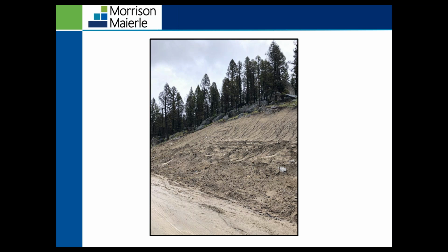So the contractor here was only relying on a silt fence, a second sediment control BMP, and they didn't have any erosion control BMP, and it resulted in that down gradient silt fence being overwhelmed and not preventing sediment from being discharged. So with this photo, some corrective actions that could take place is to roughen the surface and then install erosion control on the disturbed soil, whether that's temporary seeding, erosion control blankets, or hydraulic mulch, whatever it may be. Erosion control BMPs need to be installed on this slope to prevent sediment from being carried and overwhelming that silt fence.